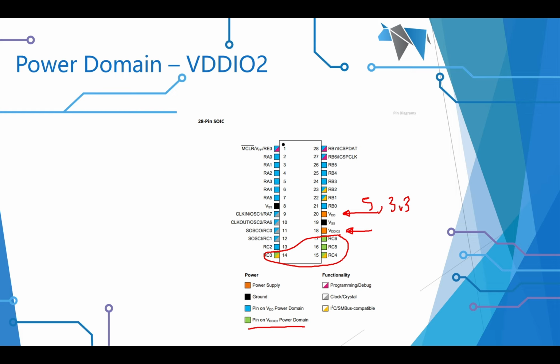So if you don't connect up what used to be connected to here, well, this used to be called C.7, if you do not connect voltage into here, whatever voltage you want, it will not work. If you don't put anything in the VDDIO2, this chip will fail, and I'll show you that failing. We'll do that in a moment.